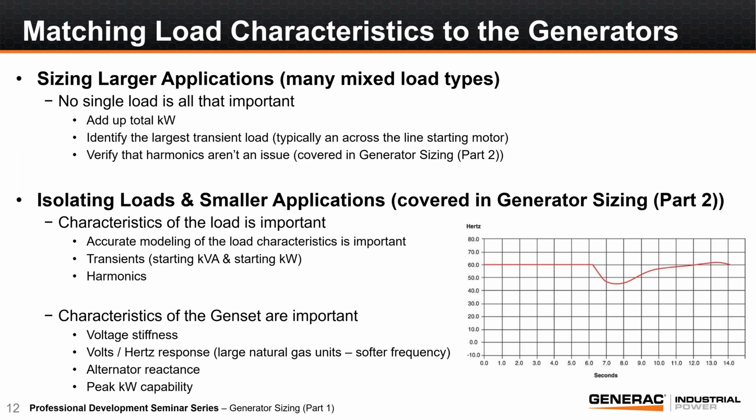When you're doing that, though, it's best if there is more than one machine creating that load. So you're generally not going to have one piece of equipment that's requiring, let's just say, 1,000 kilowatts of peak demand. In that case, if you're only going from information that you're getting from the power analysis tool or from utility bills, it's best to try to break that total kW down into a couple of different items and put them in a group. So if you have 1,000 kW peak demand, maybe breaking that down into 10 of 100 kW lines and putting those in a group to see how that affects the generator sizing. This will give the program the ability to view that demand more realistically and not looking as if all loads are simultaneously running and coming on at the same time in a single step.